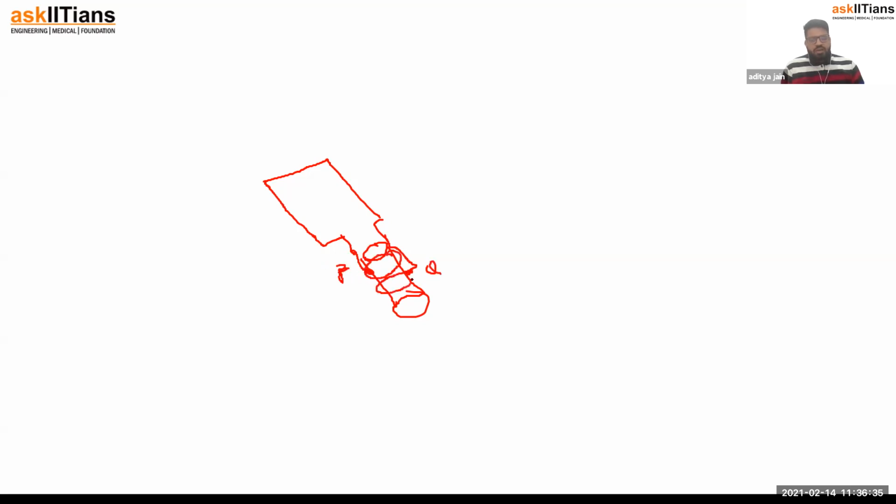Now, in place of split rings, complete rings are present. One complete ring Q is attached to carbon brush Y, and one complete ring P is attached to carbon brush X. Now X and Y are connected to an external resistor or a voltmeter, which will show the reading of voltage generated.